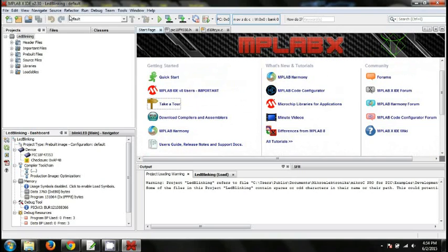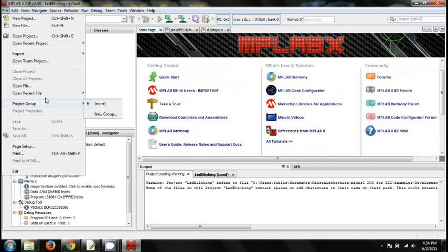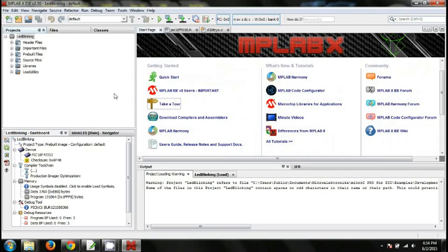And if you have MPLAB 8, if you have worked previously, you can actually import MPLAB 8 projects from here. Okay, import, and you can import hex files and MPLAB IDE version 8 projects also. So you can do that. You can basically migrate from version 8 to X just by importing them. Okay, it does take a backup of those things.